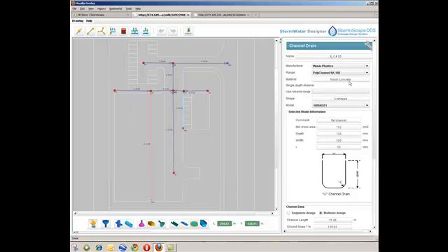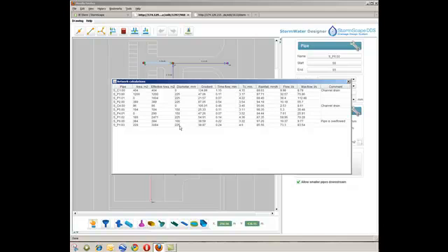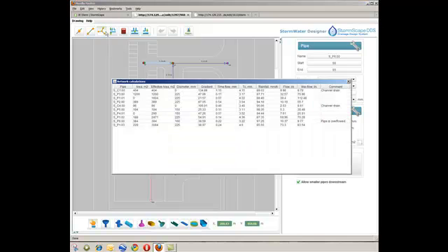To demonstrate the effect of potential flooding in part of the network, pipe SP6.0 is shown being downsized from 150 mm diameter to 100 mm diameter. This pipe serves the main car parking area in the top left corner of the detail. When the network calculations are then rerun, the pipe is shown to overflow within the comments section. The pipe in question is then reverted back to the original diameter and the network calculations rechecked to ensure the pipe is hydraulically adequate.